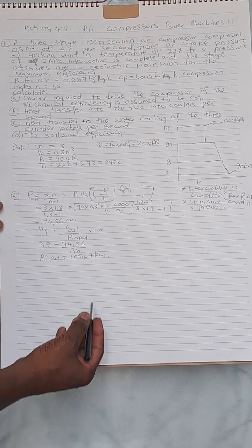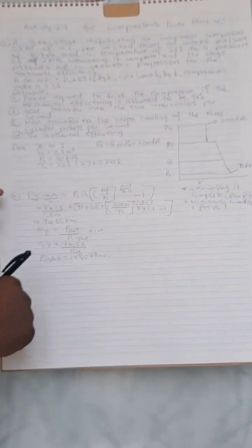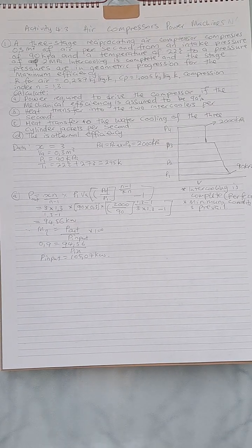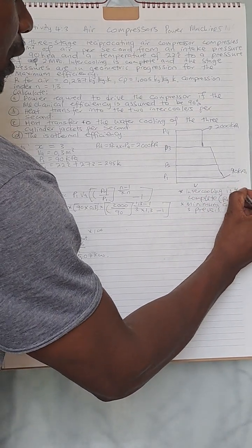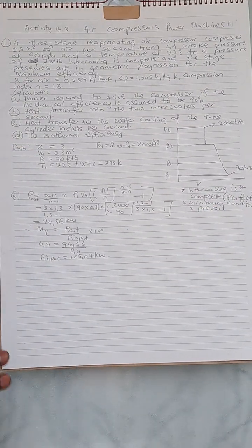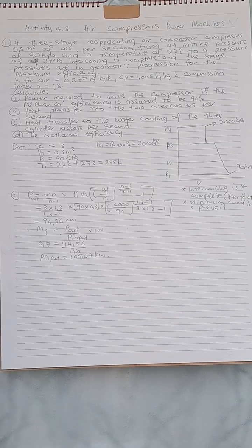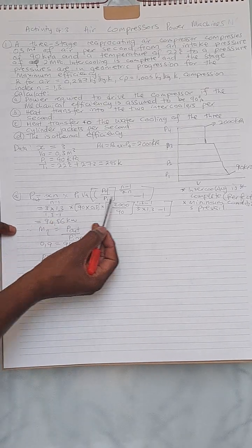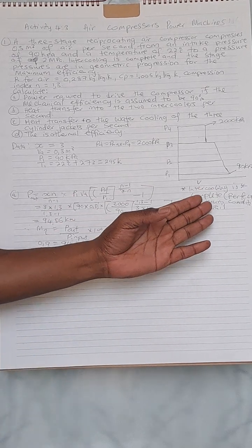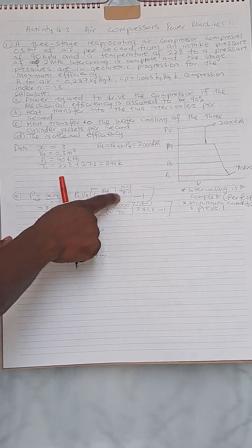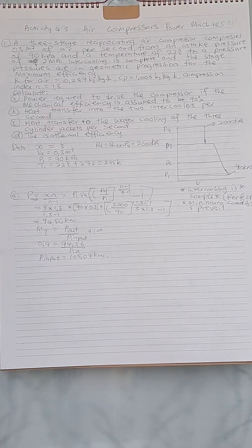the compressor. So the most important thing is not about getting the right answer, but to remember the terms which are used in the exam. Very important term, you must remember this. If they say intercooling is complete or intercooling is perfect, you must know that the formula for work done or for calculating power which you are going to be using must show the number of stages. But if the question says intercooling is not complete or is not perfect, therefore we remove our stages and then you get your answer right. This is a very simple formula.